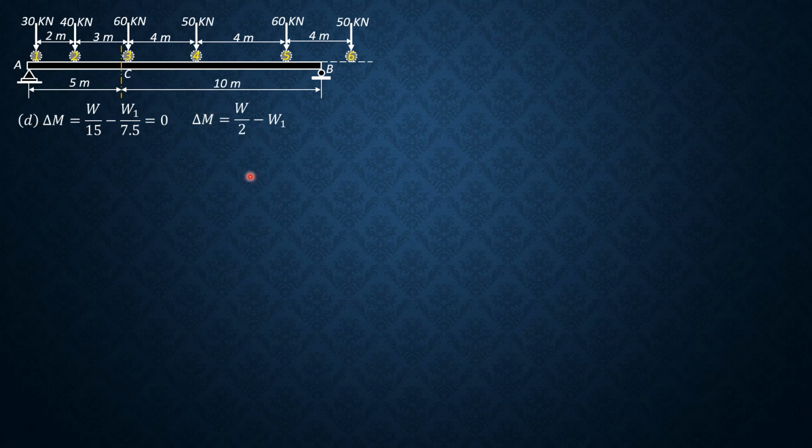So because earlier, in the preceding slides, load 3 satisfies the criterion, this time let's have loads 3 and 4 over just to the left or just to the right of the center line, because we already considered load 2 and it was lesser at C. So it will also be lesser at center because it's only 40 kilonewtons compared to 60 kilonewtons.